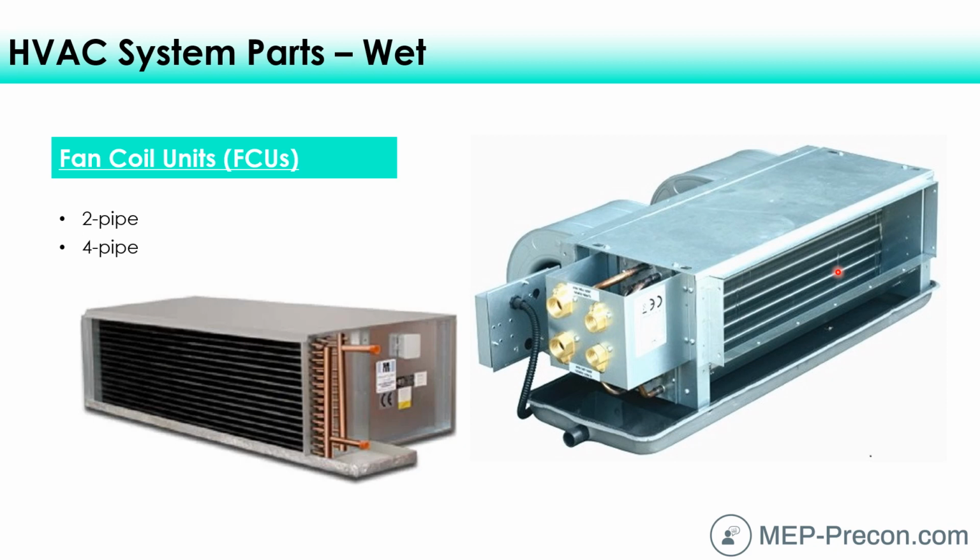And that's about it. And usually a filter. It might be a filter. If it's a ducted fan coil, it'd probably be behind here somewhere. But if you go into a hotel room and look up above in the doorway as soon as you walk in, there might be a big return air filter grill at the bottom of these. So there's always a fan, a filter, and a coil, and usually some housing that puts it all together. And that's what makes up a fan coil unit.